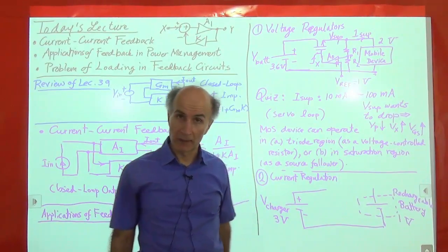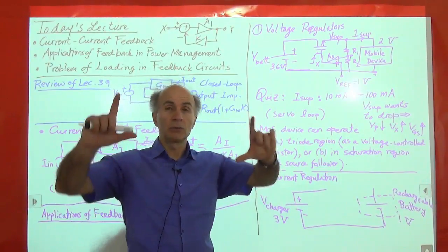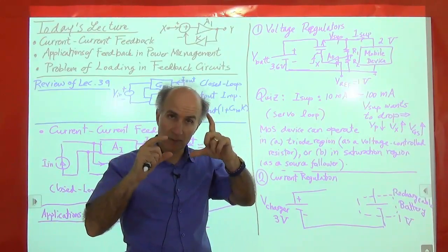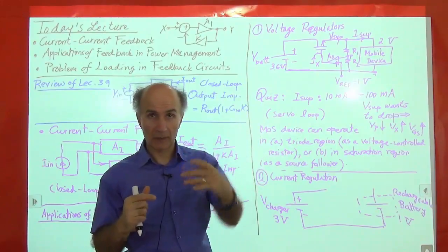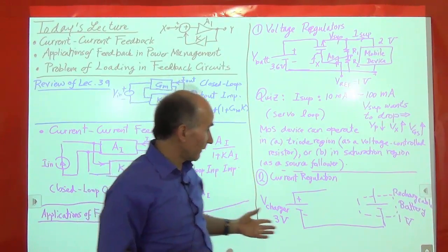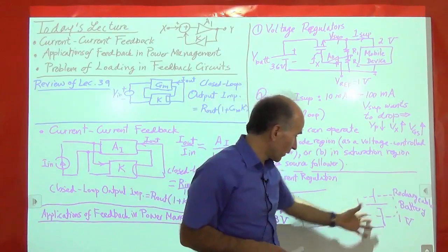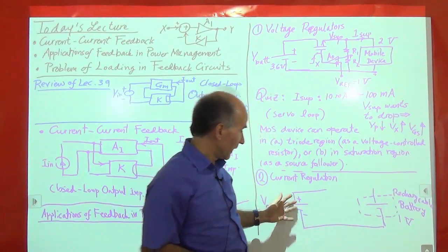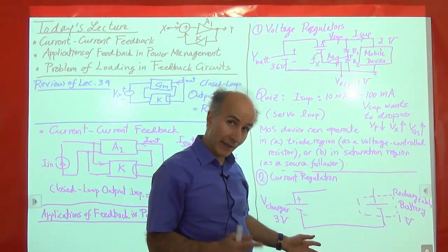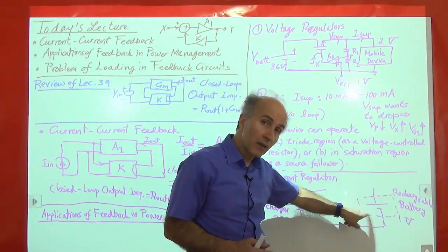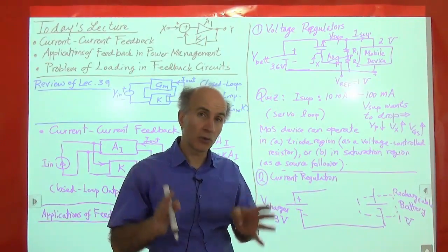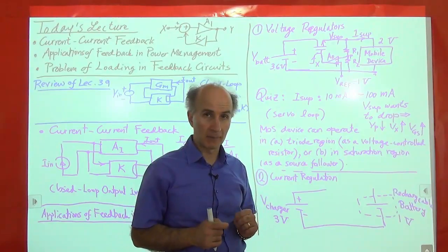No, that's not a good idea, okay? If you place 2 voltage sources in parallel, what happens if they have different voltages? Well, a lot of current has to flow, right? Ideally, an infinite amount of current has to flow. So when we have a situation like this, where this is only 1 volt and this is like 3 volts, we can't just connect them together, because a very large current will flow, and that current will damage this rechargeable battery. All right? At least it will shorten its lifetime.